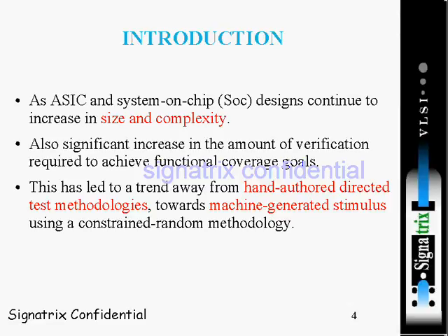Suppose you are having a 16 input decoder. In that case, how many combinations are possible? 2 power 16. That will come around 64k. So is it possible for you to generate all those 64k combinations of inputs? It's a very tedious process, right?